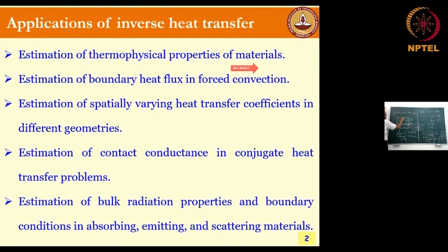So this is T1, T2, T3, T4. T2 and T3 are the interfacial temperatures. So this is resistance A, resistance B, resistance C. You learn from the best heat transfer books, and you also learned online lectures from MIT, IIT Bombay, IIT Madras, Kanpur, Kharagpur, whatever. And you estimated, but you didn't know that when two things are joined, there is a strange animal called contact conductance. This contact conductance is between the second and third. Let's say there is one more resistance called R contact, which you forgot.